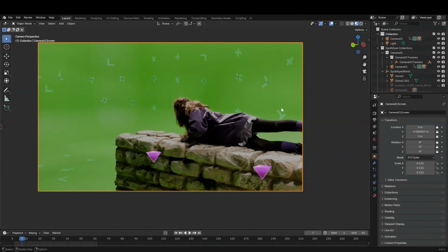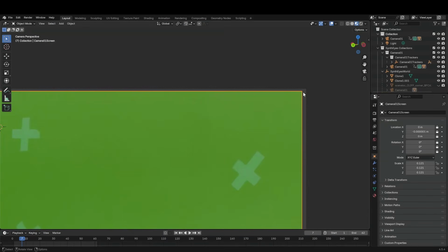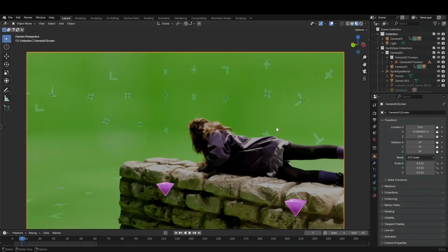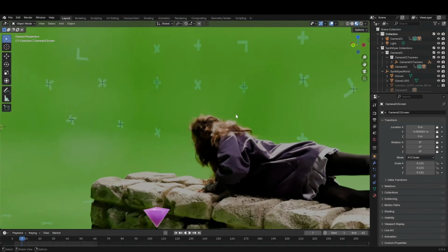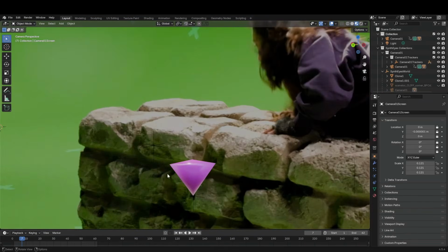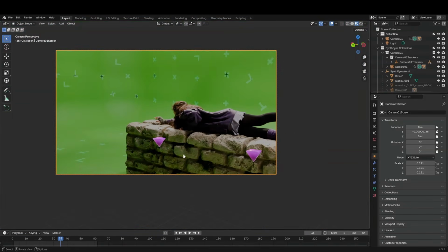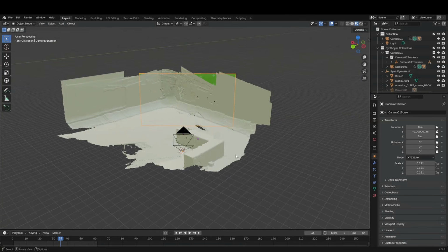And importantly, as we zoom in here, you're going to see that the imagery has a little extension here, very similar to what we saw in SynthEyes. This is because when we exported from SynthEyes, it actually generated an image plane that we can put the shot onto, and it incorporates the undistortion into the image plane. So this means that we can actually be working with our original distorted plates going into Blender, but it's undistorting them via geometry inside Blender, and that way everything lines up. So that's a very elegant way to work. So now we have something that can be correctly imported into the rest of the scene and aligned with the imagery, and we can add in rocks.